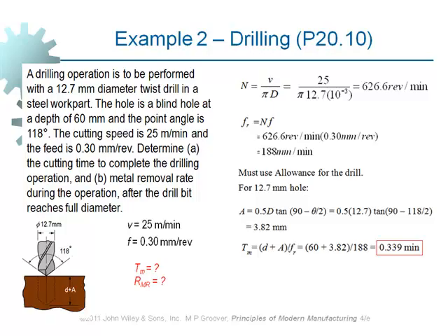D stands for depth of hole, and A stands for the extra allowance. Then we divide it by feed rate, which we have already computed. Having this computed, we can easily compute the time needed to make the hole, which is the full length plus that much.